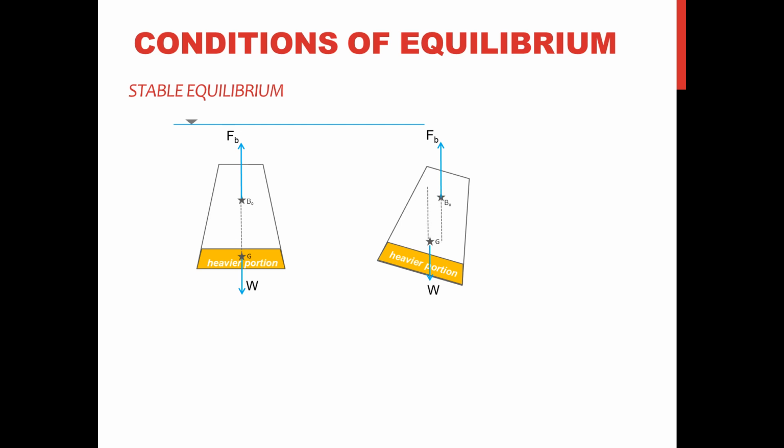So with this, there will be a distance between these two forces, and these two forces will go in opposite directions. So in short, because of X, there will be an equivalent righting moment or a couple. This righting moment is actually termed the resisting moment. By the way, this righting moment is contradicting the direction of the tilting.